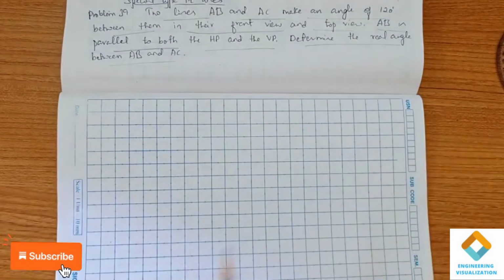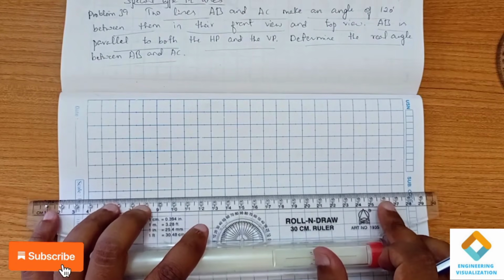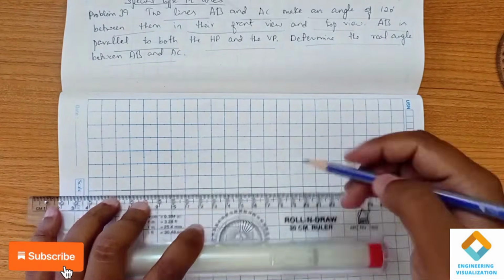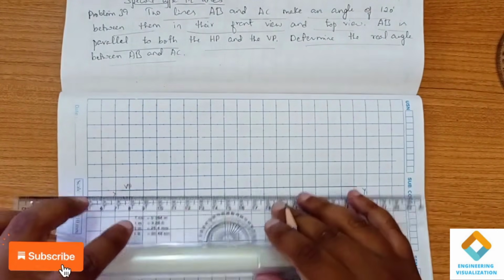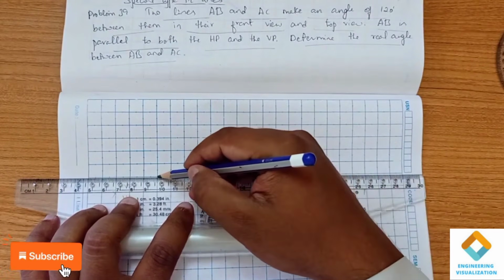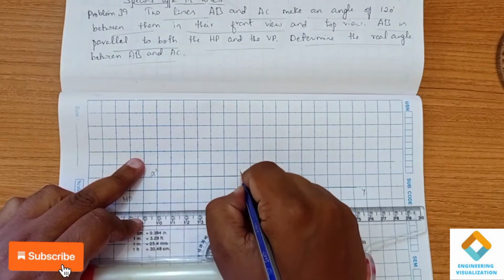So how do we do that? First we have to draw an XY line. So I will take it here only. XY, VP, HP. So first I will draw a line AB. You can see that the AB line is parallel to both HP and VP. So I will take around 60 mm length line. So this is A dash, this is B dash.